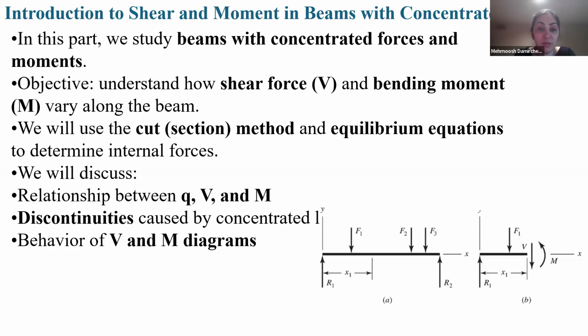In this cut method, we consider an imaginary cut at different points of the beam because we are not talking about a specific point. We are talking about the whole beam, meaning X, for example, changes between 0 and L, where L is the length of the beam.